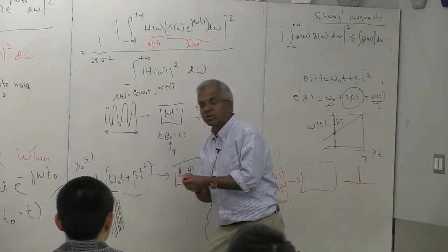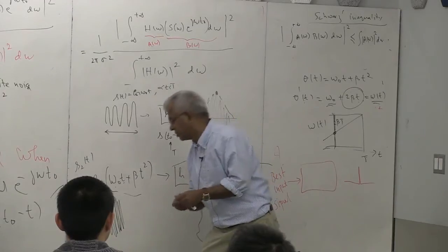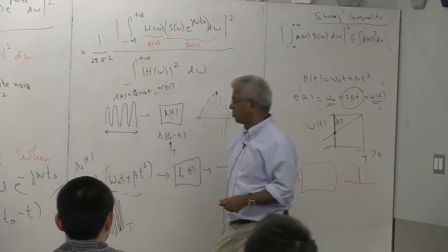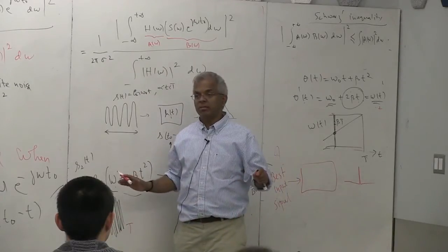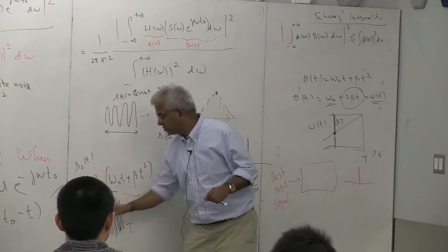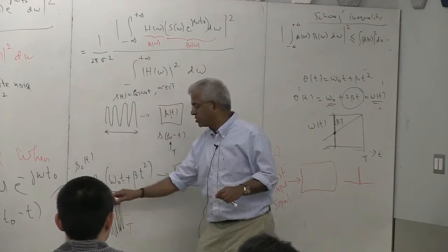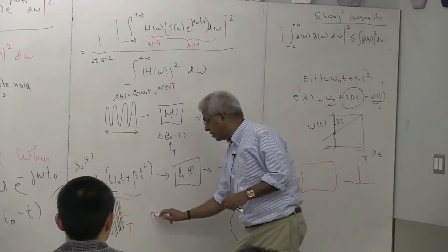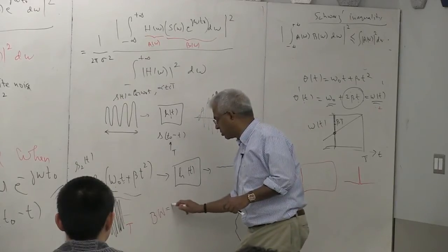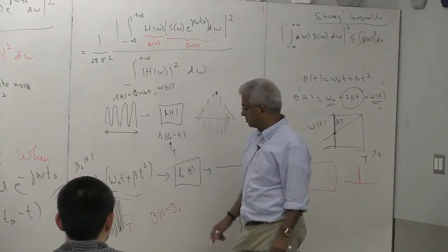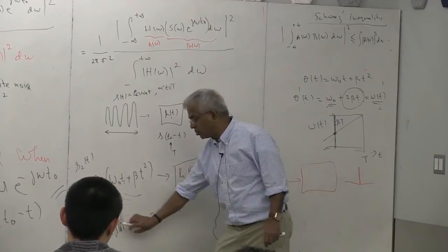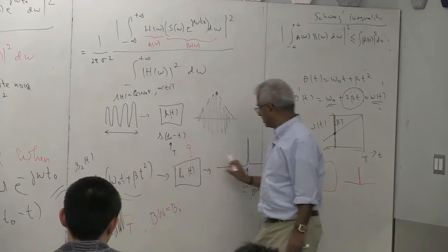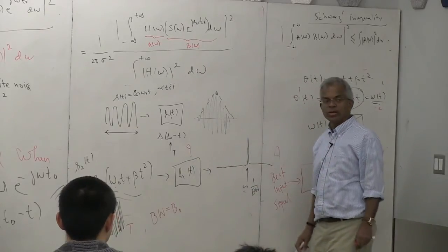You cannot compare apples and oranges, even though you can. But it should be a pulse of duration T and a certain amplitude, preferably constant envelope, and it uses a certain bandwidth. So a certain duration and a certain bandwidth. Give me the filter and tell me how much compression you can get.